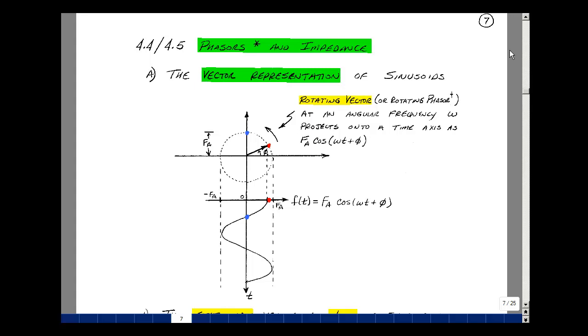to each other. We'll show later in this chapter that phasors can be manipulated by ordinary algebra rules of vector geometry or vector algebra. When the resultant vector or phasor has been obtained, its projection gives the time function solution to our analysis problem. Stepping onto the merry-go-round is called transforming the problem into the frequency domain. The resultant vector in the problem is called the frequency domain solution, and the process of finding its projection is called transforming the resultant into the time domain. This is like stepping off the merry-go-round.